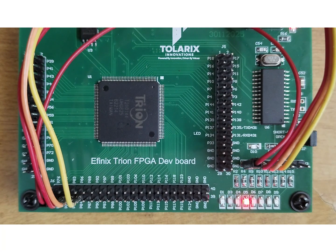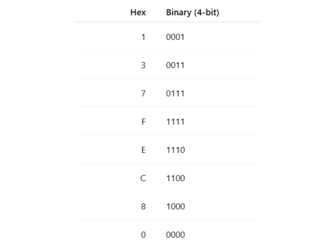First, the LED indicators display 1, which is binary 0001. Next, it changes to 3, binary 0011. Then 7, binary 0111. After that, it becomes F, which is 1111, so all 4 LED indicators turn on. Next is E, binary 1110, followed by C, binary 1100. Then 8, binary 1000. Finally, the output becomes 0, binary 0000, so all LED indicators turn off. After reaching the last value, the sequence repeats again from the beginning.